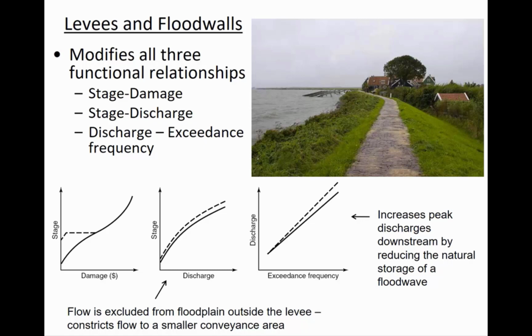So here's our river, you're putting a wall up so that the water is now up to this level, whereas if the levee wasn't there, for a certain flow rate, the water level wouldn't have gotten so high. So you're kind of confining the width of the flow.